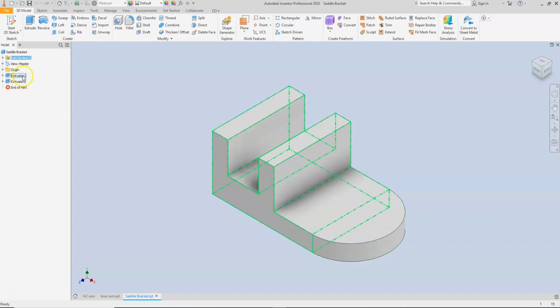You can also point to the section and you should be able to see that it highlights the view as you're pointing to it, so you can keep track of what happened during that extrusion. So let's start off by pointing to extrusion 1, and I clicked on it with the left mouse button, and then we're just going to rename this. I'm going to name this base,